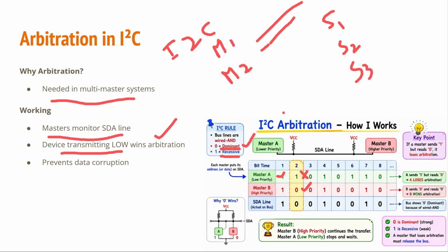If I don't use arbitration, both A and B will access and send data to slave 2 simultaneously, and slave 2 is not aware whether the received data is correct. Slave 2 receives data from master 1 and master 2, as the same bus is connected to both masters. At that time some data loss or data override will happen. That will be prevented by using this arbitration condition.